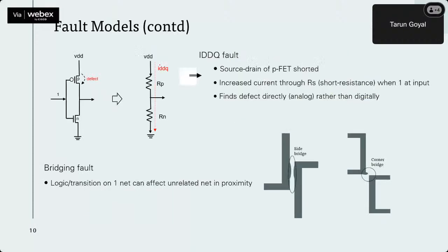Okay, coming to the IDDQ, we were talking about how, if this channel has a defect, then my current will start leaking more and this resistance becomes less. So this is how the IDDQ short starts between the drains of this P and N FET. This is the IDDQ current, which is the kind of defect we are detecting from IDDQ, where we stop the clock, reset on the capture, and measure the current between all these. If it's a short, then my current leakage will be higher. That's how we are screening the IDDQ defects.